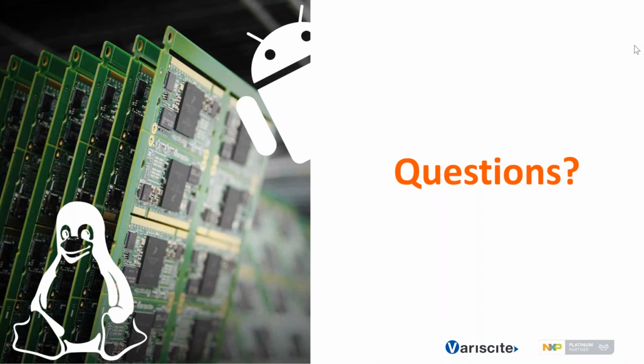Well, basically GPIO keys provide the keyboard events. So both Yocto and Android provide some dedicated open source utility in C, in native code, that can show you how to access the native interfaces from Linux. Also, the Android SDK provides dedicated APIs to access the keyboard events, so you can just wait for an event in non-polling mode. This is useful when you don't want to use the CPU too much. That's it.